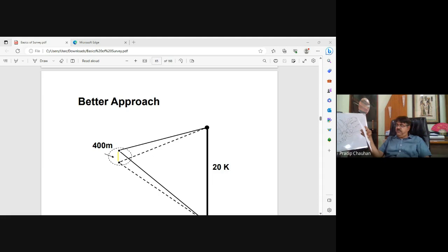Now, the equipment we have seen: there is drone survey, total station, DGPS system, then a level, an auto level, and associated prisms. Why? What is a prism? Your total station normally measures distance on a reflective surface. Every surface has some reflection, but if you need more precision, you keep a prism there. Then you get a 100% reflective surface, and the distance measurement will be accurate.